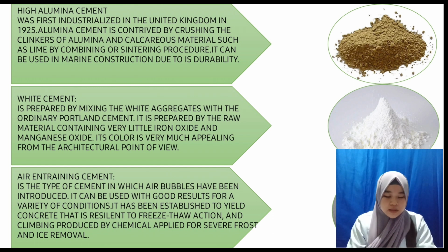Air entrained cement is the type of cement in which air bubbles have been introduced. It can be used with good results for a variety of conditions. It has been established to yield concrete that is resilient to freeze-thaw action and to scaling produced by chemicals applied for severe frost and ice removal.